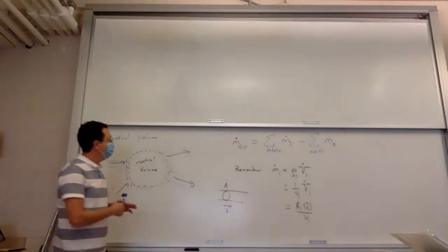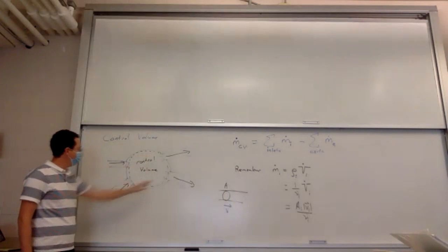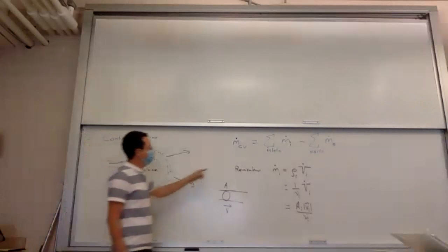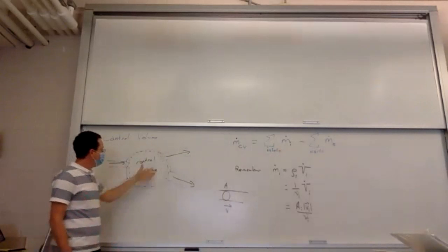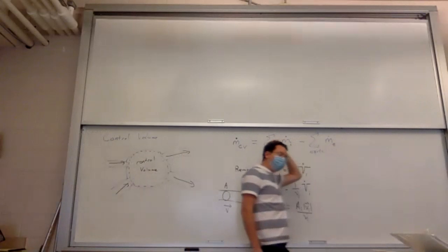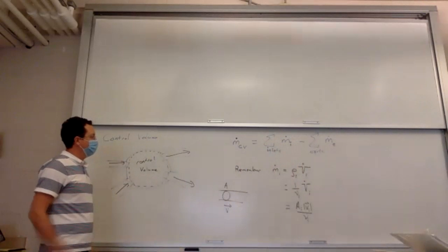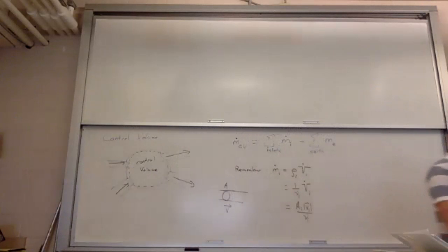Okay, so the rate of change of mass in the control volume is concentrated at the edges, the boundary. In particular, you add all the positive contributions from the inputs, you subtract out all the negative contributions from the exits. Right. So we have those kinds of equations.